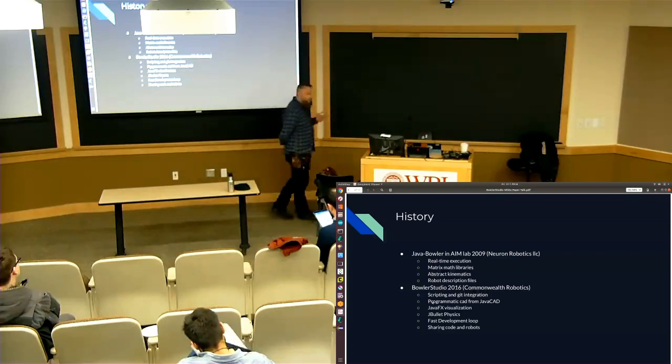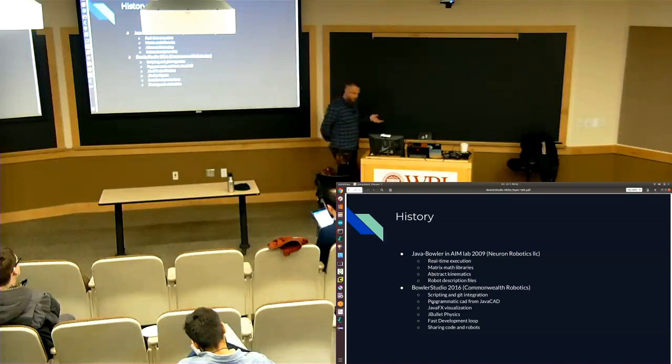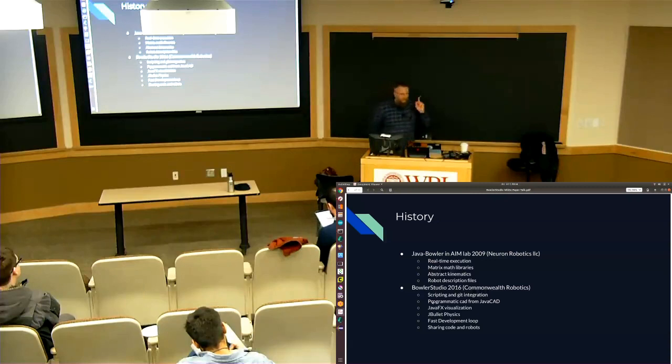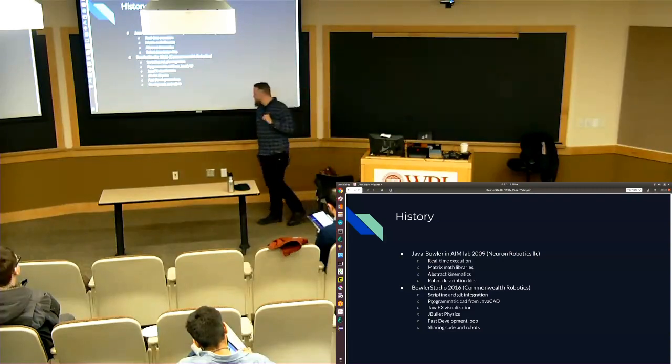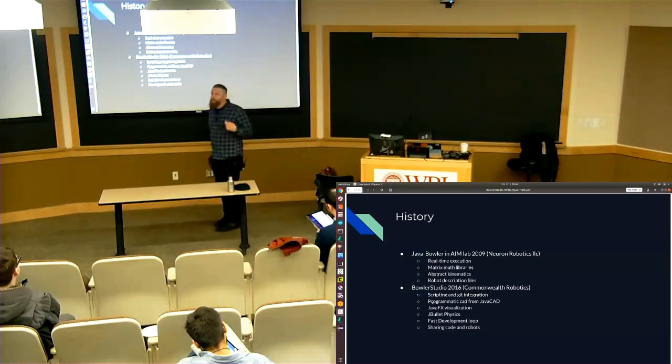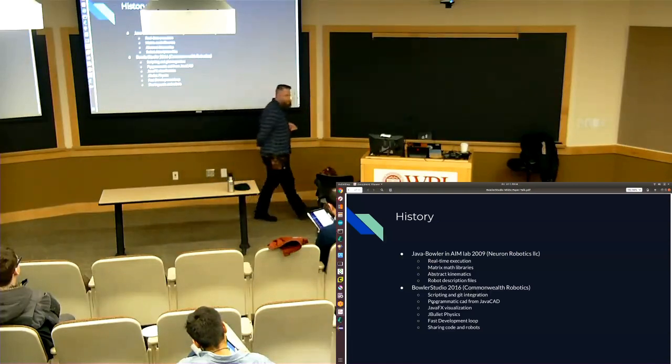DH parameters don't afford you more than one way to solve the forward kinematics, now do they? So if you can define your robots that way, boom, half that problem is solved for you. And the other half, the inverse kinematics, should be something that can be swapped out from device to device.